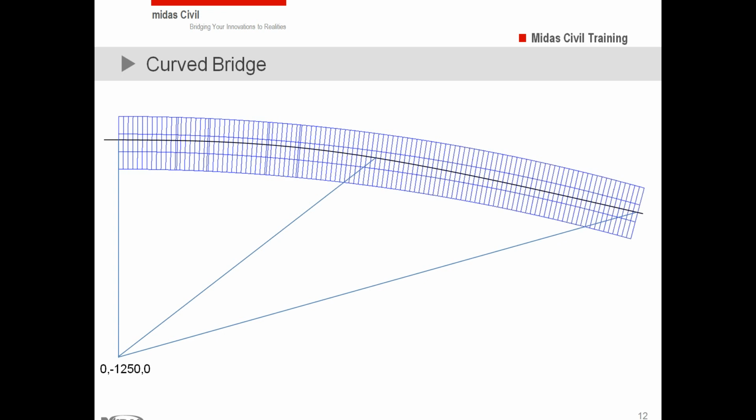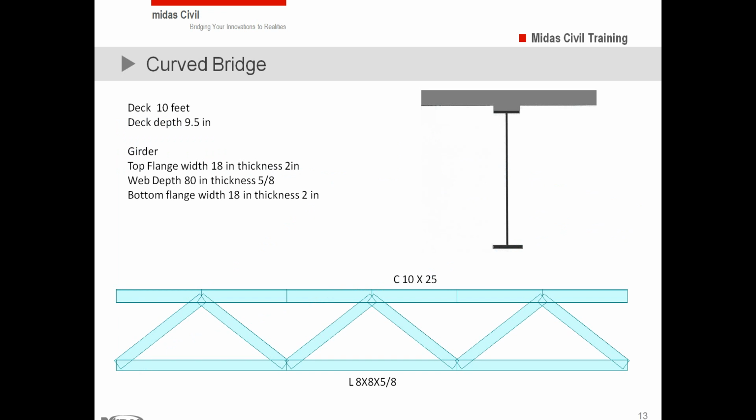So what I'm gonna be doing is I'm gonna create 4 nodes at the location of the girders at the origin, and then I'm gonna use the extrude feature to create the entire element. And this is how the cross frames look like. So now let me start the modeling of this bridge. It's gonna be pretty interesting, so I want you guys to focus a lot here.